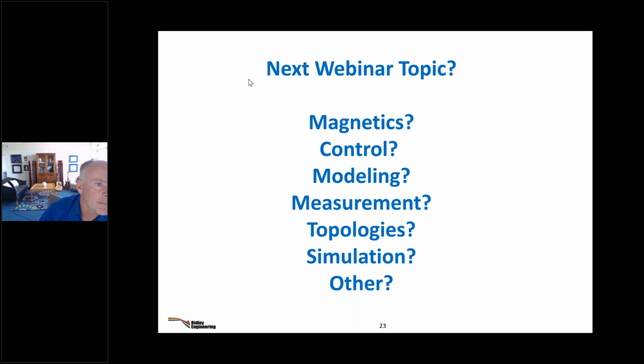How can I optimize my magnetics design for proximity effects? Well, you do multiple designs. We looked at whether we can do all the choices for you: foil wire, multi-strand wire, Litz wire, and optimize the proximity losses. We could loop through that and find the answer, but then you never learn anything. I prefer to choose the wires and the type of winding knowing how you're going to put this together, so that you don't blindly choose foil because it comes out better. You have to know the price of foil at the same time. Same thing with Litz. If it doesn't make a big difference, don't use it because it's more expensive.